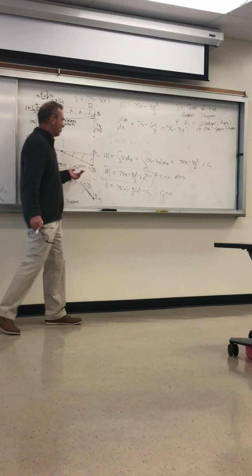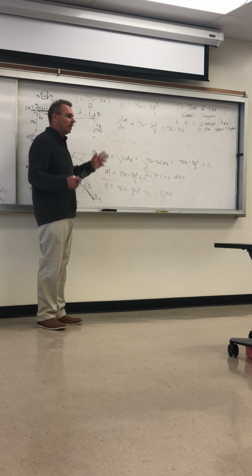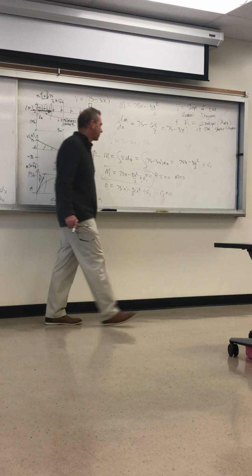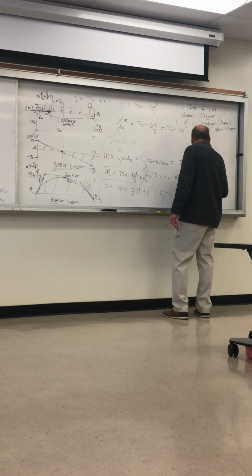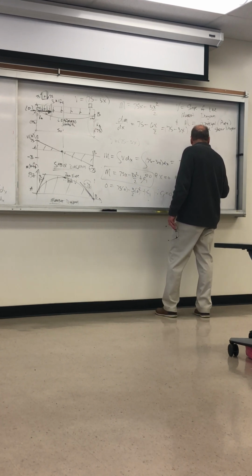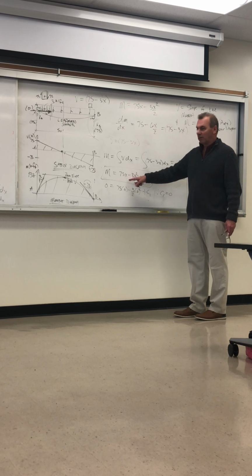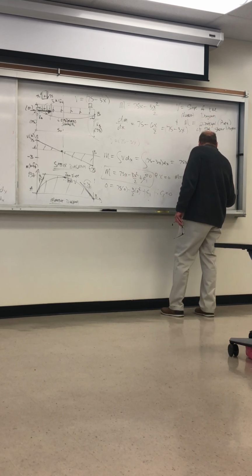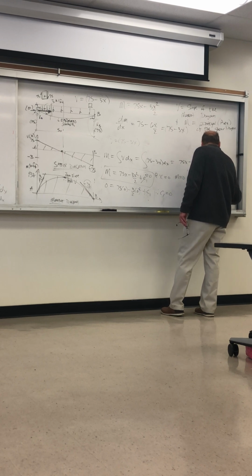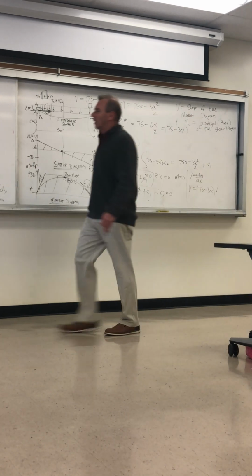Now a structural engineer won't solve the moment expression this way, but still you understand the interaction between shear and moment. And then, of course, we can just say the shear, as I did above, is dM/dx. So the shear is equal to, now I'm just going backwards again, taking the derivative of the moment expression with respect to x. You can see I get 75 minus 3x. So we get back the shear expression. So what's interesting is now you go over and look at something like this.